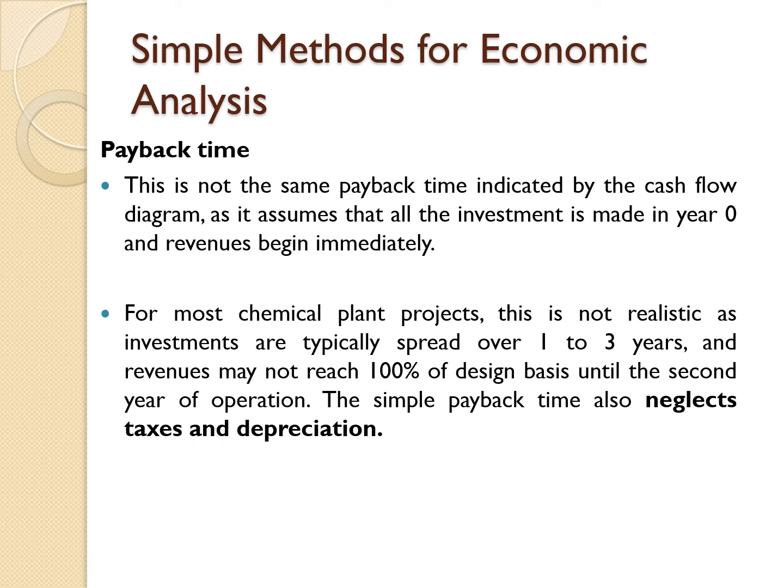Okay, this payback time is not the same as the payback time indicated by the cash flow diagram, as it assumes that all the investment is made in year 0 and revenue begins immediately. For most chemical plant projects, this is not realistic, as investment is typically spread over 1 to 3 years, and revenue may not reach 100% of the design basis until the second year of operation. For the simple payback time, they neglect taxes and depreciation.